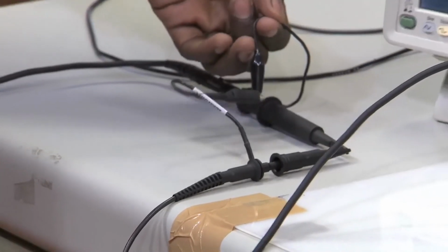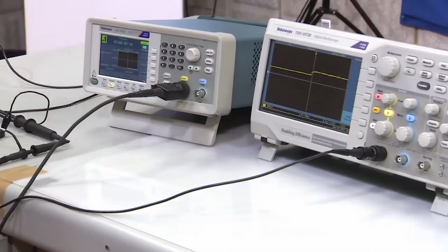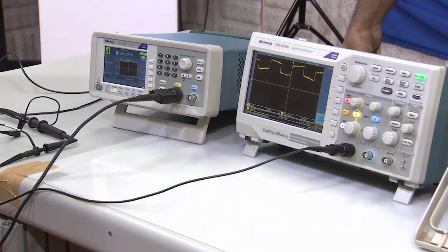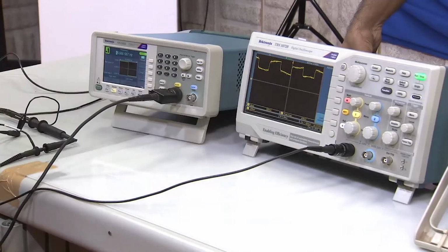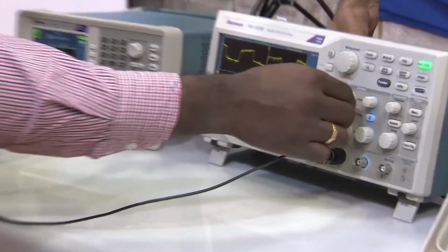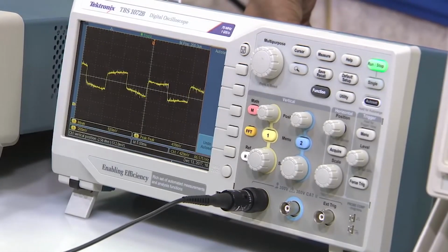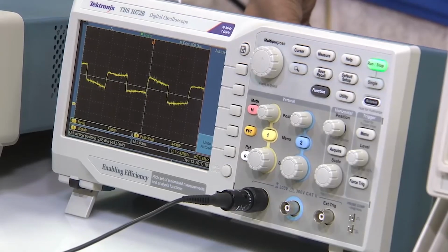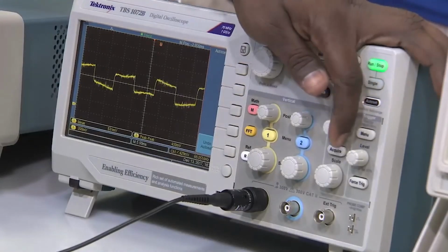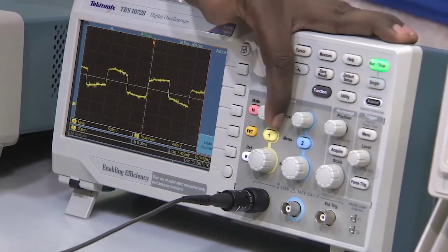When you make the connection, now let us see how it looks on your system here, please. Yes, you can see the square wave. Now, can you please move it down. There is a function for positioning, one is vertical positioning and one is horizontal positioning. By vertical positioning he is moving the vertical position. Can you please show it? See, this is horizontal. When you move the horizontal, the waveform will move along the horizontal axis. When you move the vertical, it moves along the vertical axis.